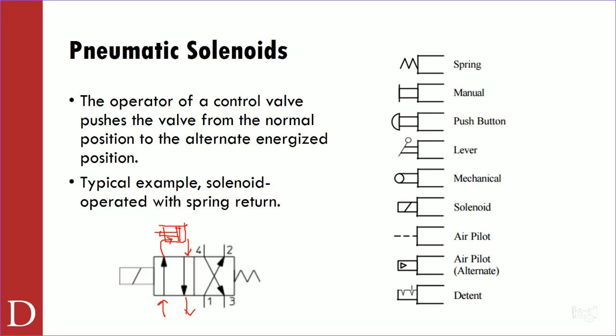If you look at those little robots, on the front of them, you'll see a little solenoid valve where that blue tubing goes. And then coming out of that blue tubing, you'll see some shiny gold little mufflers is what we call them. Do you see the little gold mufflers on the side of the solenoid valve? What are those mufflers for? Yeah, they're exhaust. If you don't have those mufflers in place, when that solenoid is hitting, all you're going to hear is a constant steady air pressure.